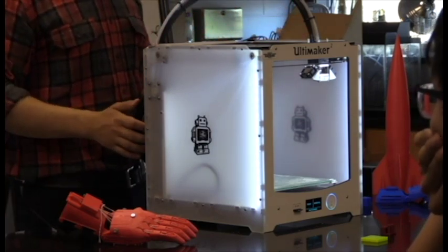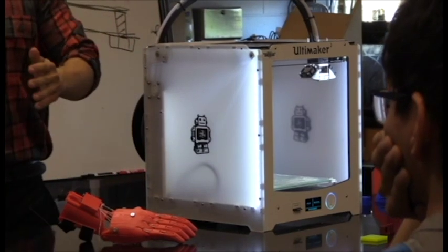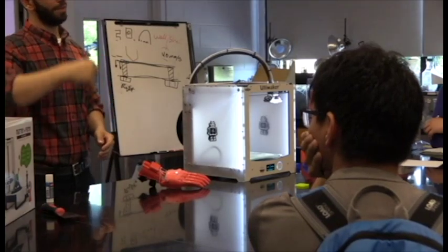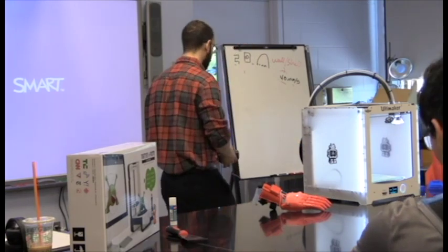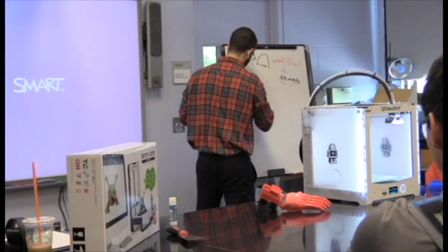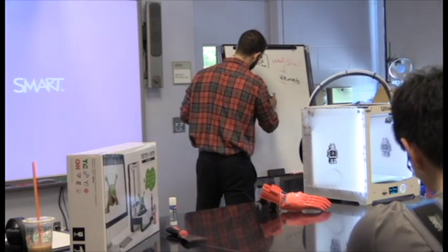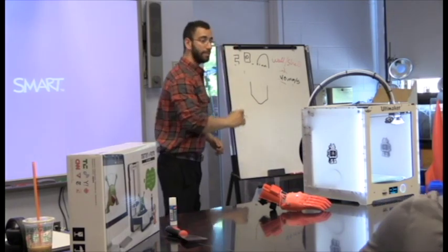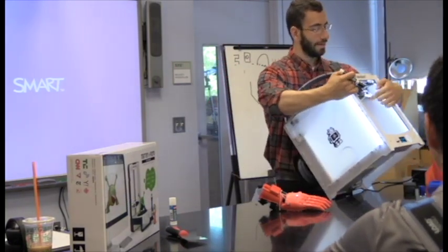Next thing we usually want to check for is the filament, okay? The biggest, most common issue when the printer starts printing but nothing comes out is that the nozzle is clogged. There's nothing going to be on it. The hot end. The most common problem that can happen with the hot end, or as we say, the nozzle, looks kind of like this. This is, by the way, what I'm drawing right now.